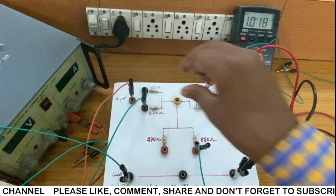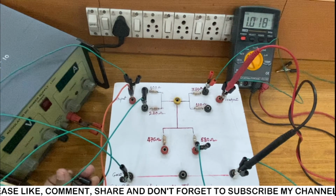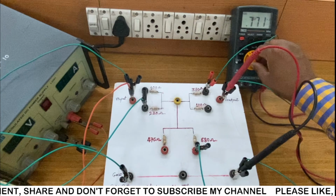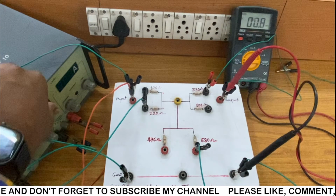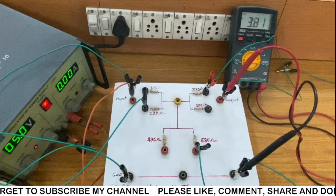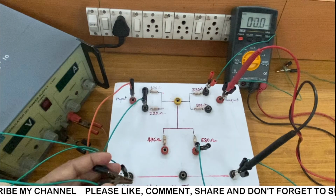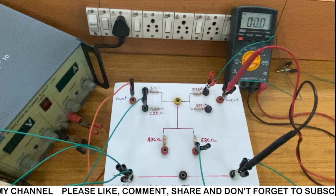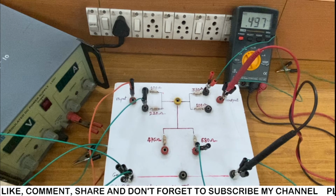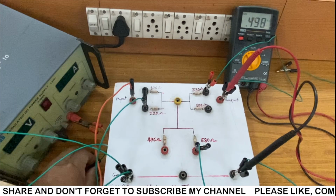If you have to do the next combination, I am going to take it to be a 220 ohm. So similarly again we are going to connect the power supply. I am going to measure the DC voltage, so I am going to make it on. Now you can see here the VTH is 3.81. I'm going to make it off. I'm going to short the R1 resistance with R3. Going to put it in resistance measurement, so it is indicating 0.498k or 0.497k. So it is 498 ohm or 497 ohm.